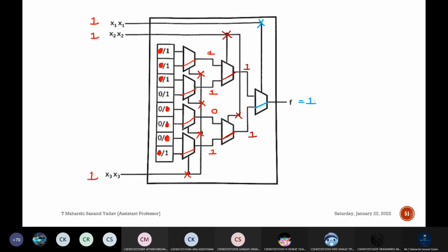So this concept is the same as designing the multiplexers, like you are designing a bigger size multiplexer by using smaller modules, like an 8:1 multiplexer by using 4:1 or else 2:1.